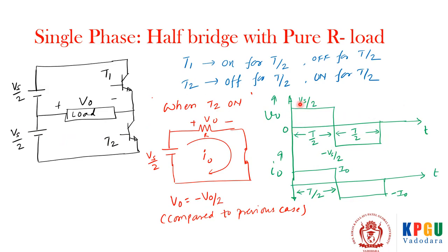Though it is a square wave, it is made up of a fundamental sine wave plus its harmonics. So if we filter the harmonics, you get more or less a sine supply from it. So this is a square wave inverter, but this is the very fundamental principle of how the inversion or DC to AC conversion is achieved.